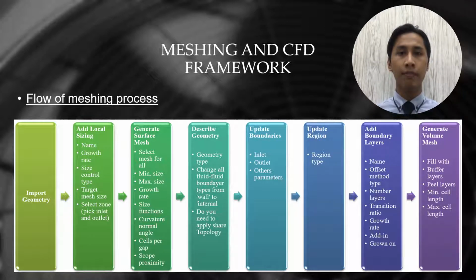Moving further, declare the diffuser and outlet vent as velocity inlet and pressure outlet while assigning other boundaries as wall. Set the boundary layer at 3 for each wall and keep other values at default. Lastly, assign a minimum and maximum size value in volume mesh at 14 and 112 while using polyhexcore subdomains.